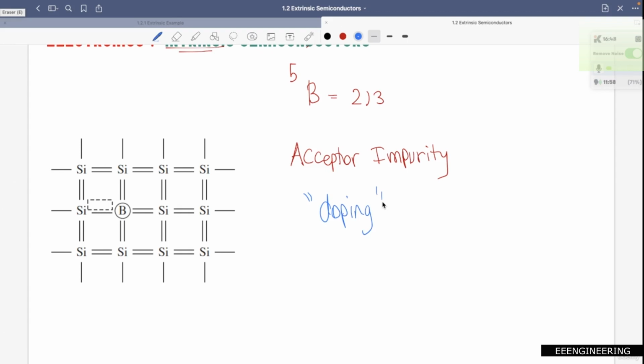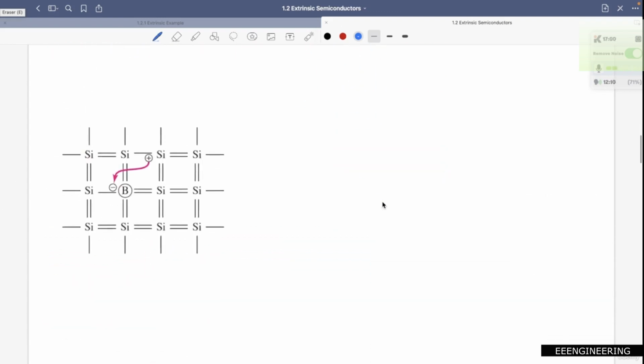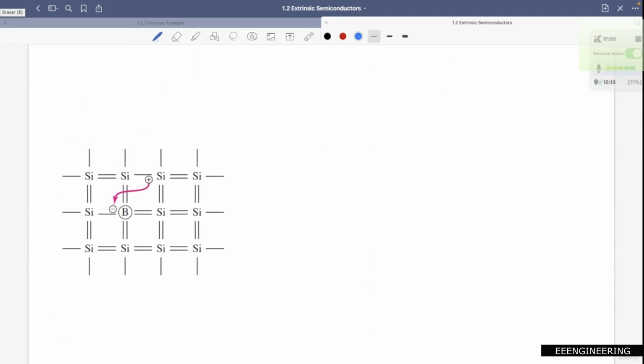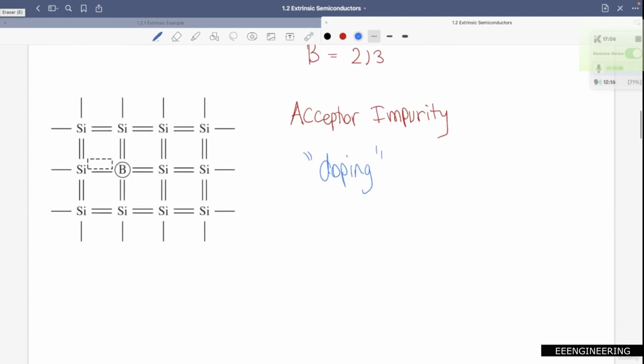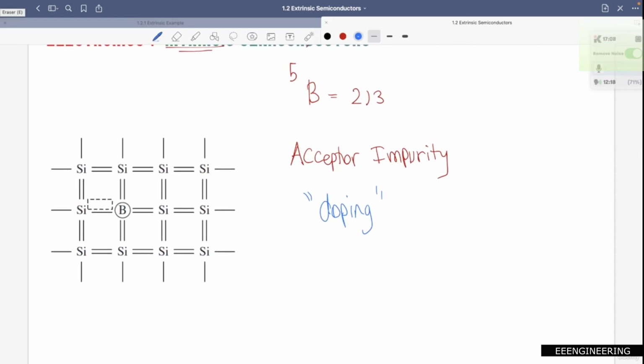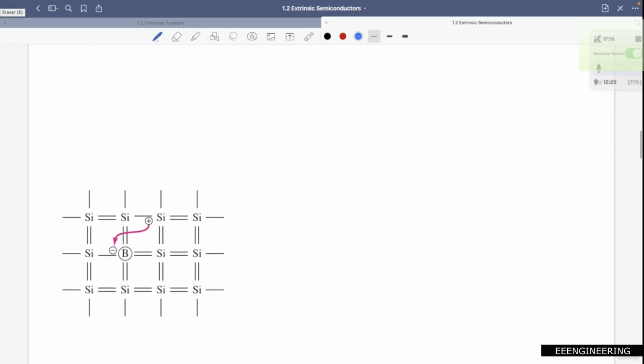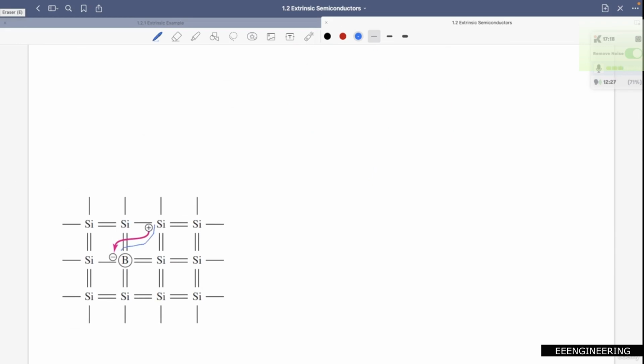The relationship between electron and hole concentration in a semiconductor is determined by an equation involving our intrinsic carrier concentration, which is, by the way, really easy. And I forgot to show you the figure we have in here, but it is not that important. The idea is this: here we have a boron atom, and it misses one covalent bond in here. So we're getting that electron from another silicon and creating a positive charge over there, meaning we're creating a hole in the silicon atom.